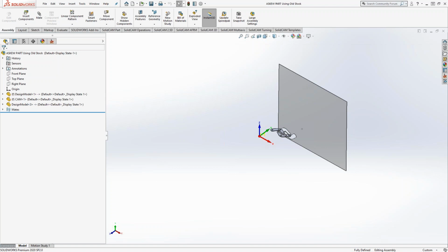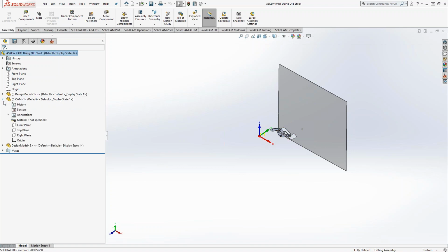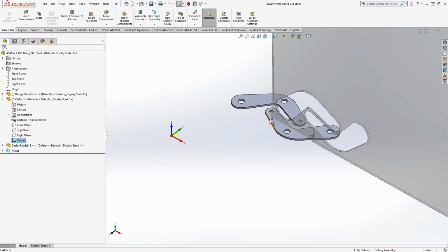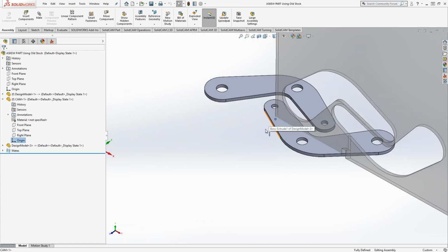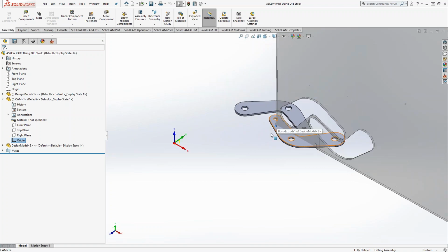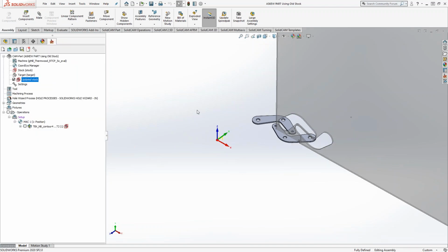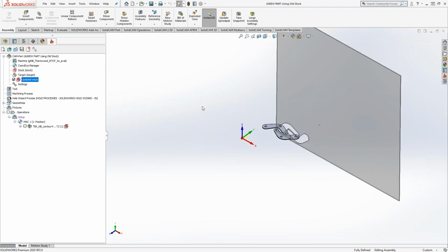Another thing you'll note is if we go to CAM and I just highlight our origin, again, the origin is at the top corner of that stock, but it's over there, not where our Mac 1 position 1 is. So it just means that the STL was created under a different coordinate system. In the past, what you would have had to do is maybe go back, save it as a different file, manipulate it. You might have even had to create a dummy Mac 1 position 1. You'll see some of the older videos on our YouTube channel that reference that.